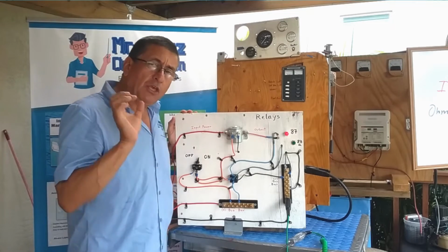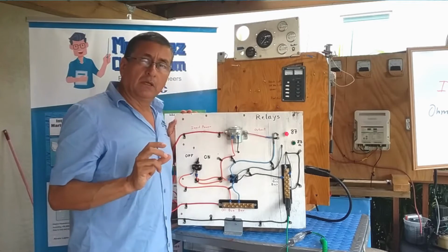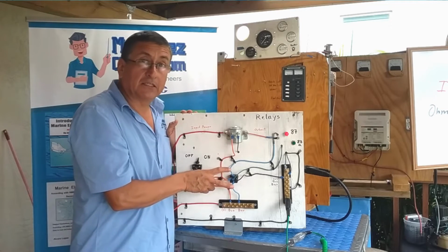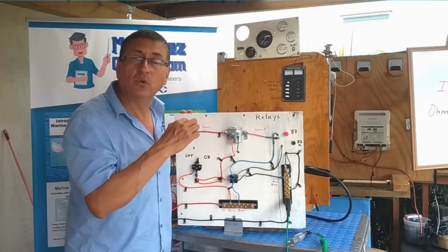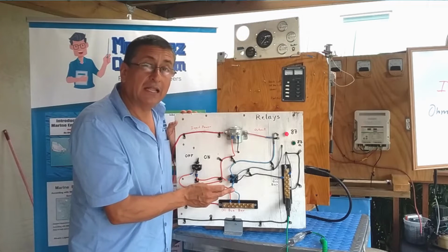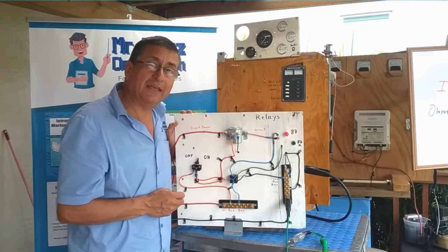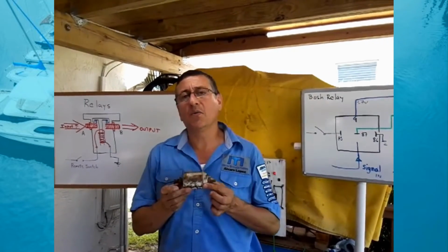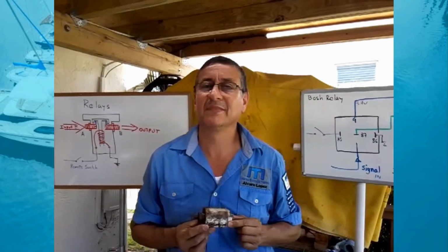The bus relay can be used for two purposes. To activate equipment, you can use 30 and 87, the external. To stop engines, you can use the connection between 30 and the middle one. The middle one is 87A. Now we are going to continue with the solenoids.